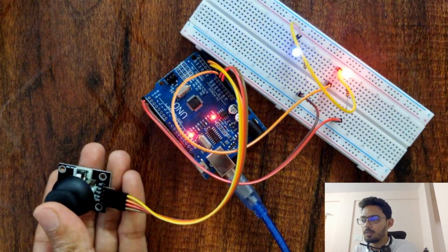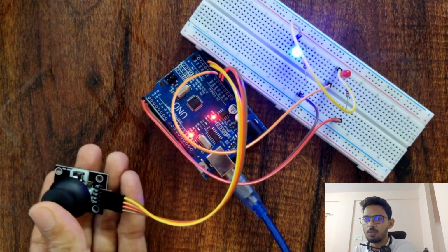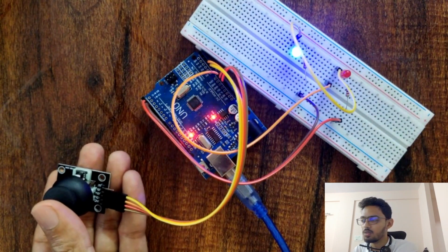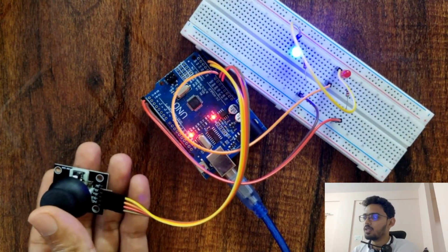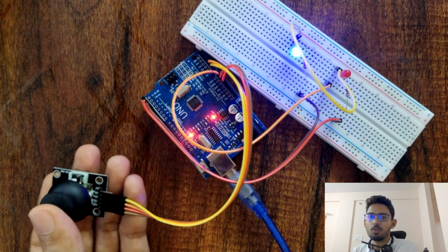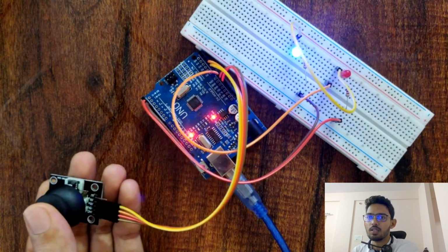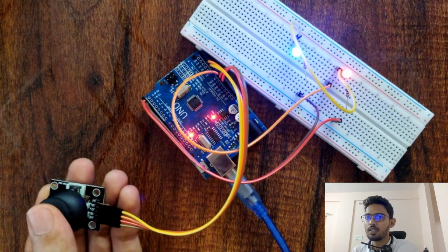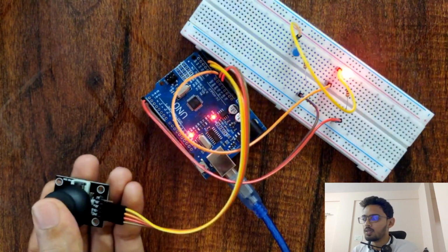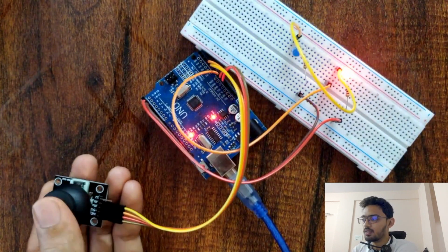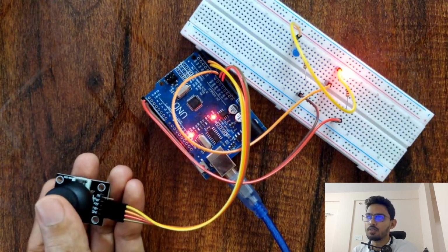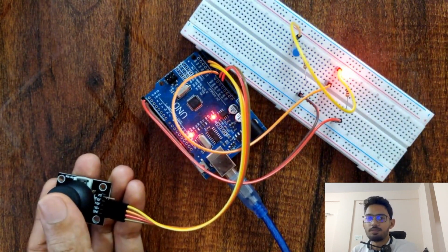If we keep it to the max, then we see only the blue LED glows, the red one goes to 0, in which case the output of the comparator would be coming as low, and therefore only the blue LED is glowing. If we move it in the negative y direction, slowly the red one starts blinking, and if we keep on moving towards -y, the duty cycle of the on period of the red LED increases.